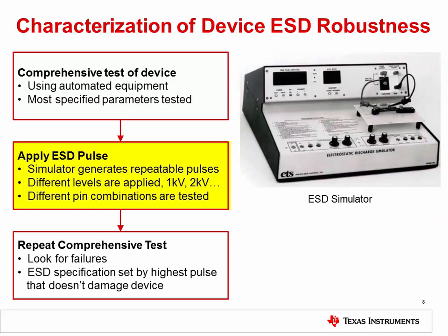The specific characteristics of the ESD pulse are controlled by the test hardware. For example, the amplitude and ESD model can be selected. Various ESD models will be discussed later, but in short, the ESD model sets the capacitance, inductance, and charge of the ESD pulse to simulate a real-world ESD event.